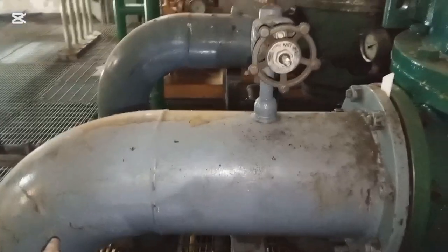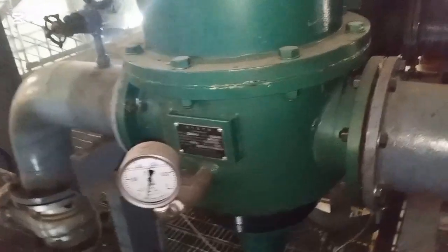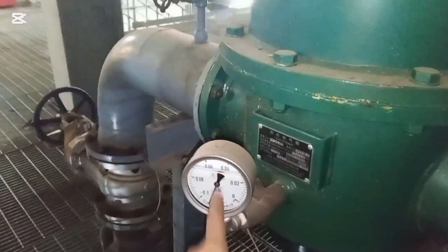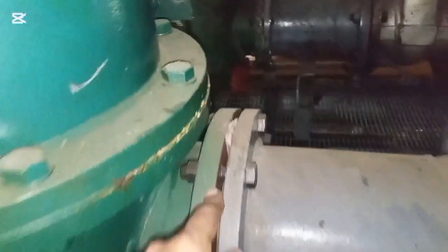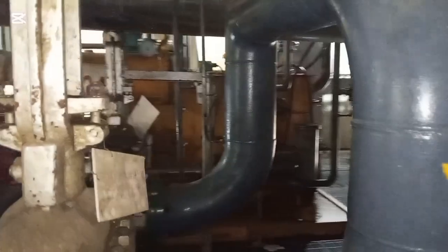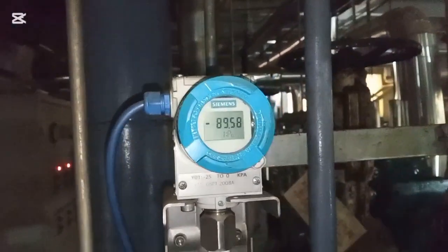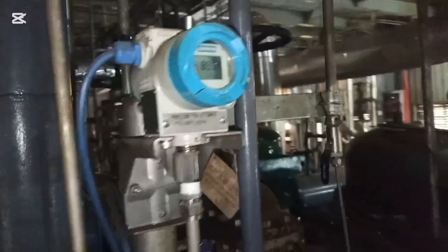When we start the water pump, then here a pressure arises, likely 3 to 4 kg per centimeter square, and here we change the diaphragm in different lines and different shapes, and we followed the vacuum from the transmitter as well as our DCS system. Then finally, when the vacuum is sufficient, that means more than 85 kPa, then we thought that the vacuum is okay.